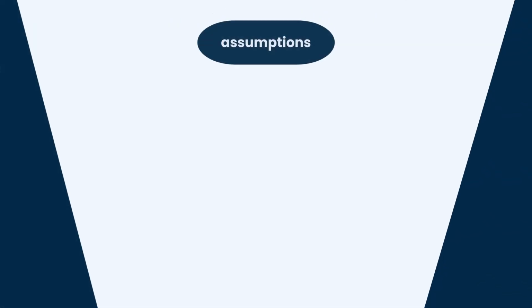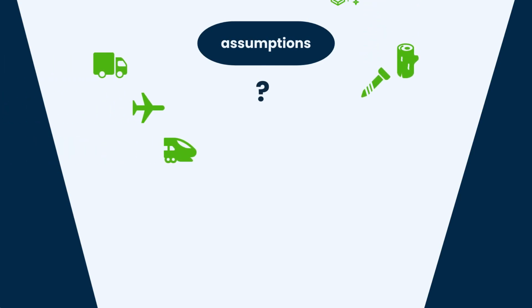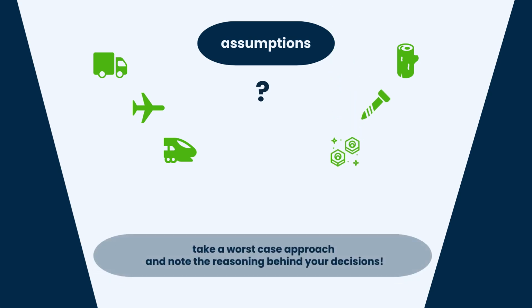Second, it's important to realize that every LCA requires some assumptions. For example, you might not be able to exactly retrace all transport of your materials, or there is no representative data set available for some of your materials. Don't let this stop you. Take a worst-case approach and carefully note the reasoning behind your decisions.